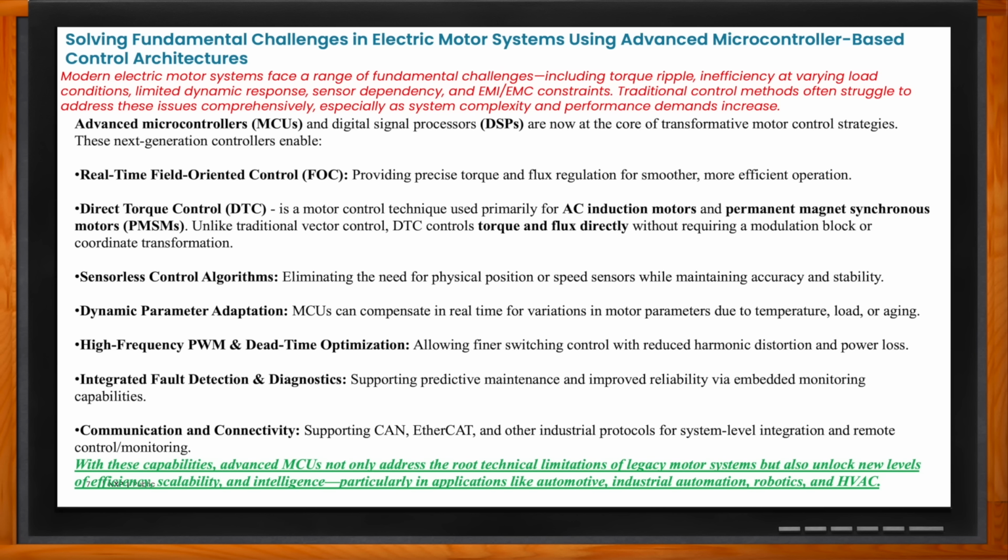But later on, specifically the Japanese realized the connection between the MCU, the power amplifier to drive the motor, and the motor. And the power amplifier actually has to be changed depending on the size of the motor and the need of the motor, what it can drive, and try to make it seamless and transparent. This is where the connection comes in with an MCU. The MCU doesn't really care what size of motor it's driving, but the amplifier does. And that MCU has to adjust to the combination of the amplifier and the motor connection.